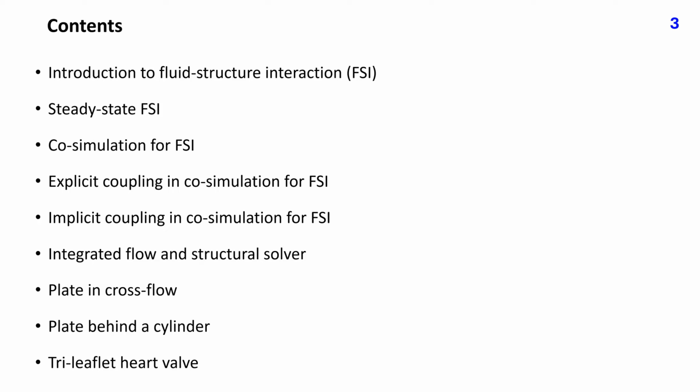First, an introduction to fluid structure interaction is given, highlighting the different solution options for steady state and transient problems. The sequential solution approach, which is suitable for steady-state fluid structure interaction problems, is outlined next, using aircraft wings as an example. Coupled simulation with different codes for the computation of fluid flow and structural deformation in an explicit and an implicit version is the next topic, followed by a discussion of the optimal approach with an integrated, implicitly coupled solution approach with both solvers being part of the same code.